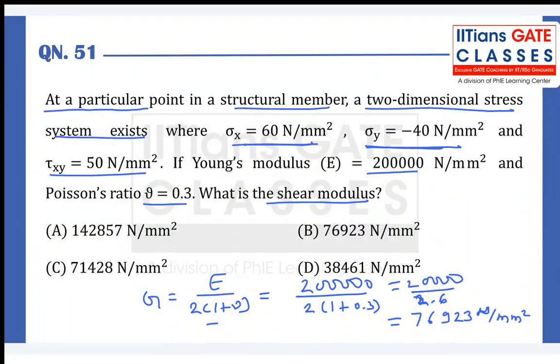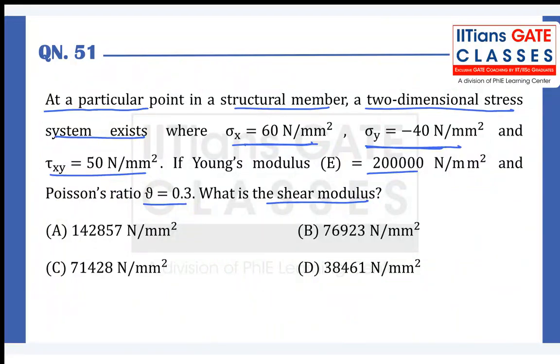Now guys, you don't just remember this. Now I'm asking one more thing. In this question, if they ask to find the bulk modulus, Mr. Uttam, what is the bulk modulus K? In simple words, you can tell K in terms of E and nu. It is E upon 3 into (1 minus 2 nu). Am I correct? Yes.